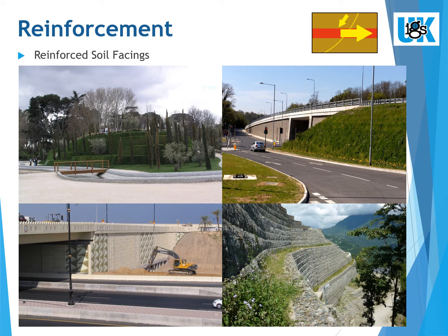Any facing applied to reinforced soil structures is purely to provide an aesthetic finish and prevent localized erosion or unraveling of the face. Facings consist of vegetated steep slopes, gabion finishes, modular concrete blocks, or concrete panels. Since the soil and reinforcement work in harmony, the increasing cost with increasing height is relatively insignificant, making extremely high structures more feasible.